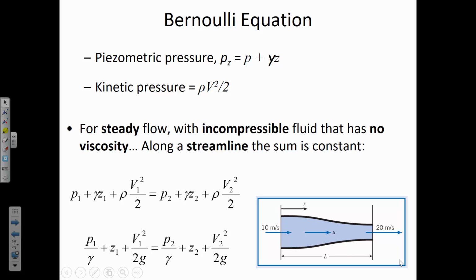And so I understand the notion, but actually the pressure is lower in the confined section, and we can go into the lab and prove it, and we will go into the lab and prove it. We'll plug in a pressure gauge, and we'll watch as the pressure decreases at the confined, contracted section, and then the pressure goes back up again when it re-expands after going through a brief contracted section. So it's the opposite of what sometimes you might think. Bernoulli's equation says that energy has to come from somewhere. For you to have an increase in velocity, you must have a decrease in pressure.